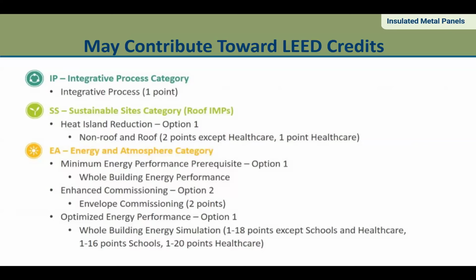Like I said, you're done all in one fell swoop with sheathing, insulation, and vapor barrier. And the other part of it is once that building is dried in and insulated, your interior trades can get to work straight away. They can't start work until that's all completed. So if the sheathing's up, your electrician and your plumber can't get in there until the insulation and everything else is up. So again, it helps compress the schedule in multiple ways.